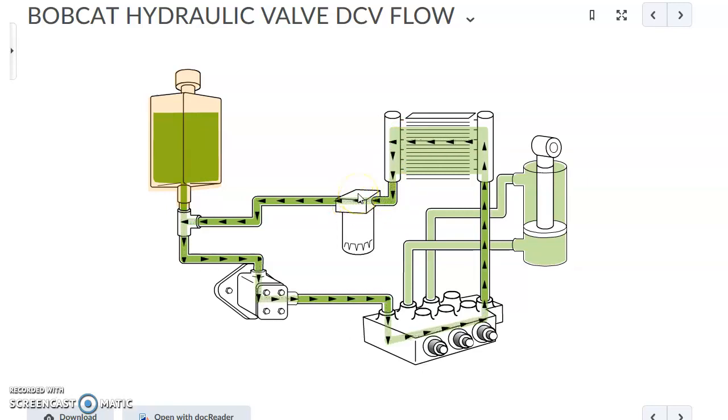So generally there's a couple of different radiators back there stacked together. And then we've got the return oil filter, which appears to be a spin-on element, a full flow cartridge type filter. Full flow because all of the returning oil is going through that filter, so 100% of return flow is filtered. It wouldn't be a high efficiency filter, probably 30 or 40 microns.